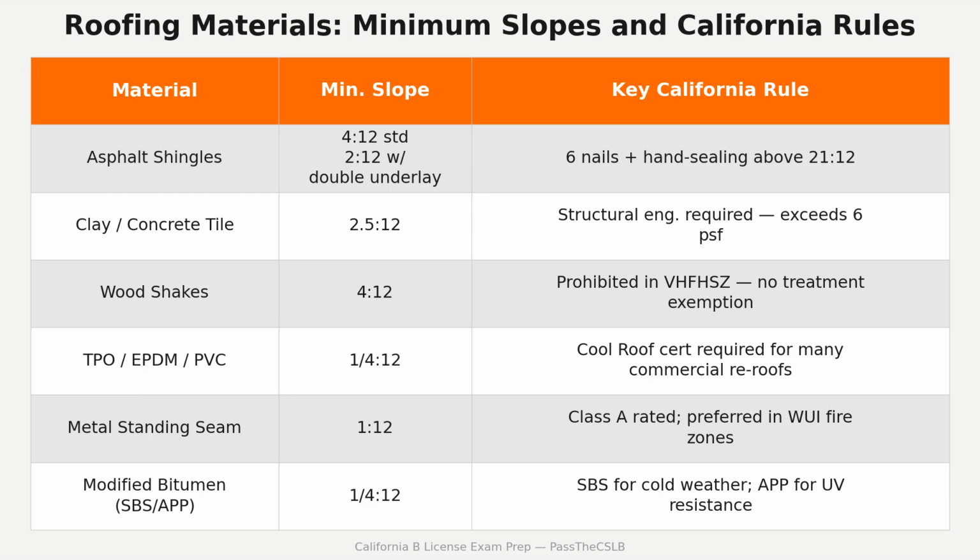They tie the two exterior walls together and resist the outward thrust generated by the downward weight of the rafters. They prevent the walls from spreading apart. Ceiling joists typically serve this function simultaneously. Collar ties are in the upper 1/3 of the attic space.